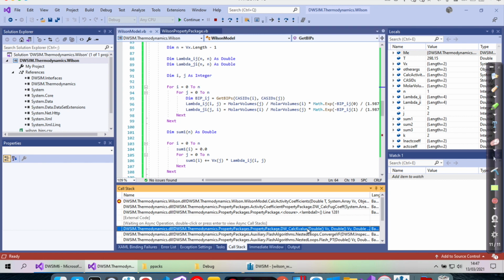I find that this limitation is very good in design, but it's a drawback when you're dealing with real data. Yeah, you cannot do it directly, but you can use some Python scripts to force or bypass the equilibrium calculation, or force the fluid to be into a single phase. It is possible to do, but you have to write a script to do that, because you can associate a Python script to the calculation routine.